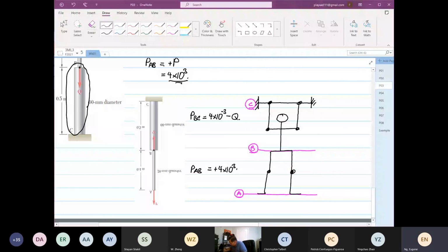If we pull a load down here, there is P, right? And we push down here upwards, there's Q, right? The hand is going to feel the what? So we still apply the tension and compression. It's going to feel the P minus the Q, yes or no? That's where when you do a chin-up exercise, if someone gives you a push at your butt, it is so much easier, yes or no? So that's why member BC feels the P and the Q.